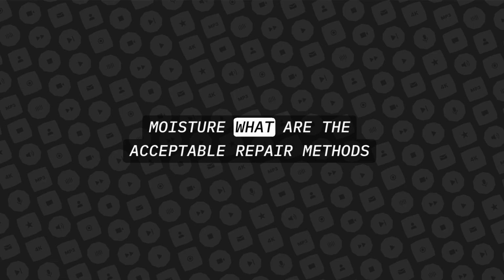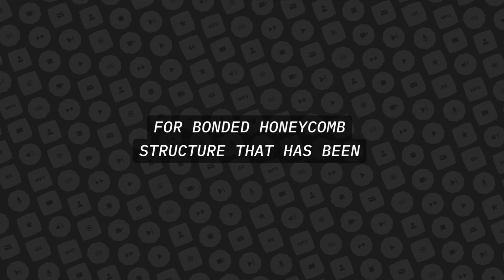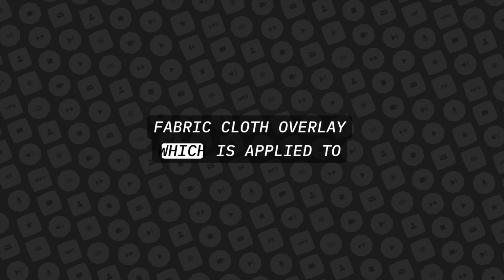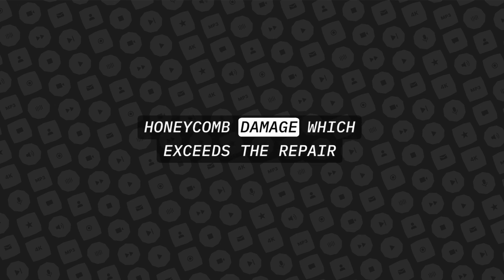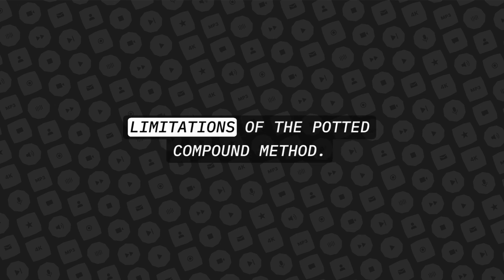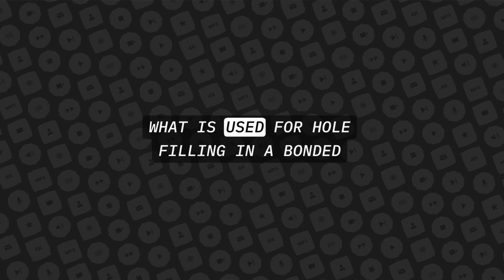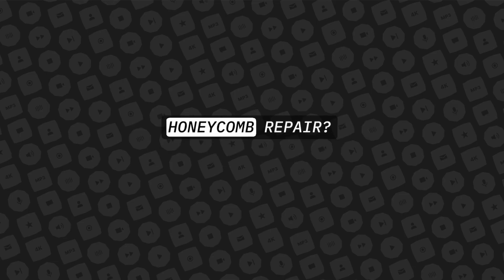Moisture. What are the acceptable repair methods for bonded honeycomb structure that has been damaged? 1. Potted repair method. Or 2. Laminated glass fabric cloth overlay, which is applied to honeycomb damage which exceeds the repair limitations of the potted compound method. What is used for hole filling in a bonded honeycomb repair?